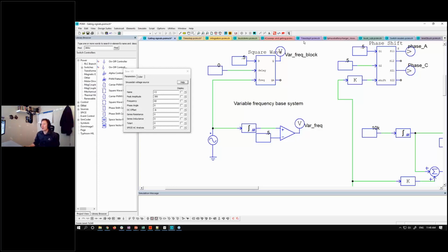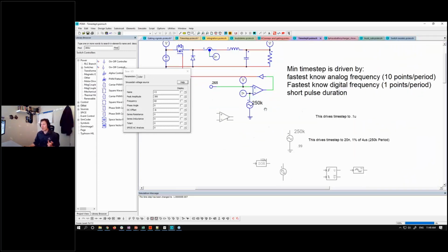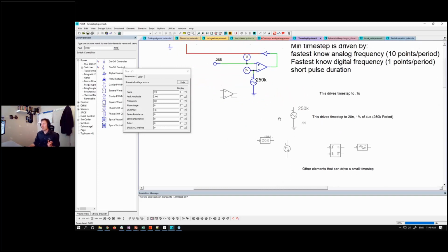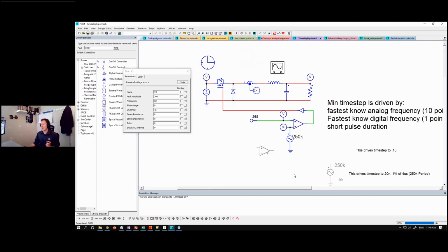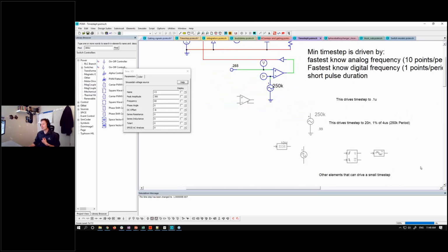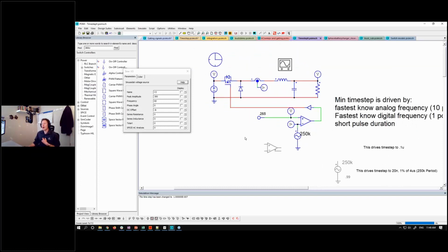Wheels will fall off the bus if you try to have a really coarse time step and there's a whole bunch of other things happening in the system. If too many things are happening inside of the coarse time step point, you start to run into issues where that adjustment isn't going to work too well. So definitely, start coarse and work smaller as you add in more complexity.